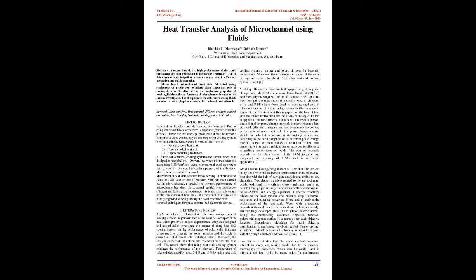The microchannel heatsink was first introduced by Tuckerman and Pease in 1981. Later on, lots of research work has been carried out on microchannels, especially to increase the performance of the microchannel heatsink. Microchannels have a high heat transfer coefficient and less thermal resistance. This is the main advantage of the microchannel heatsink. Microchannel heatsinks are widely regarded as being among the most effective heat removal techniques for space-constrained electronic devices.